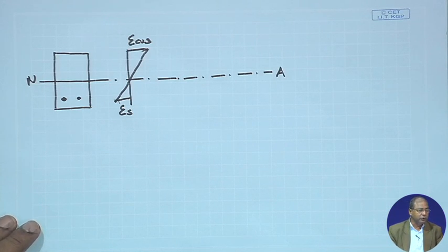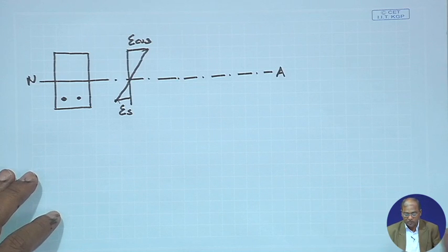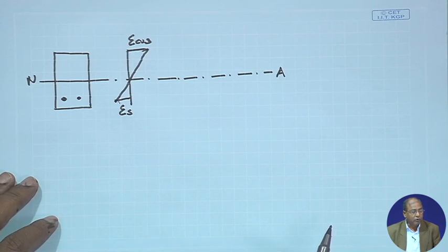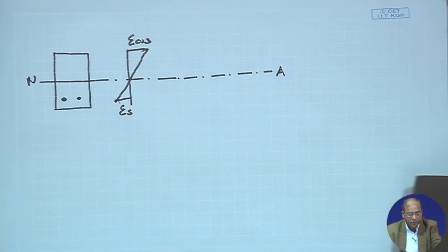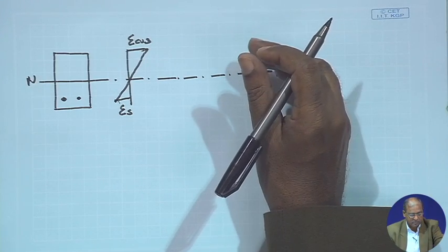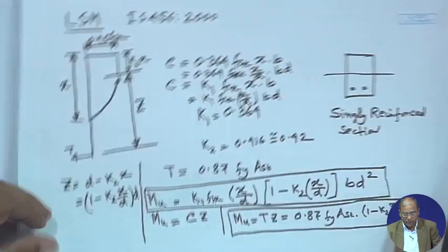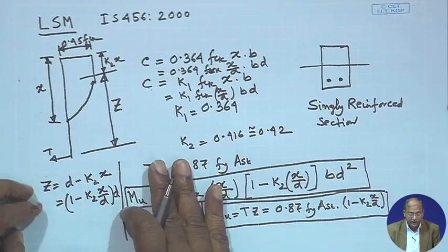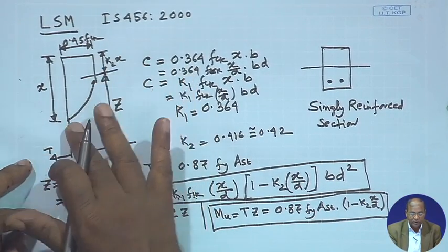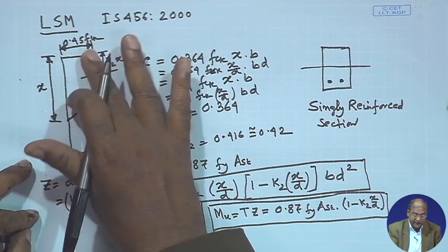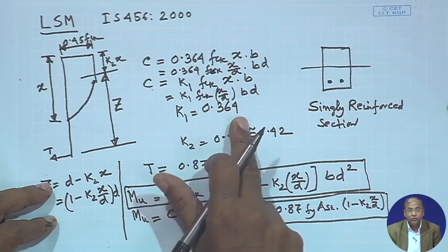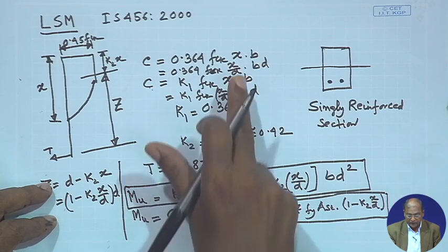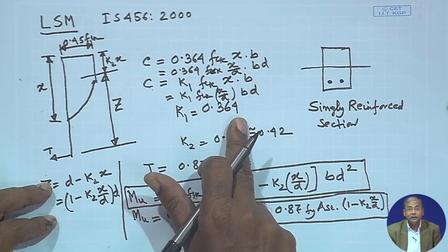Now recall our objective is that here we would like to make a parabolic distribution. From the parabola, just see why I have taken this one, this is the parabolic one. This area I would like to make 0.364 FCK, that particular one we are having.